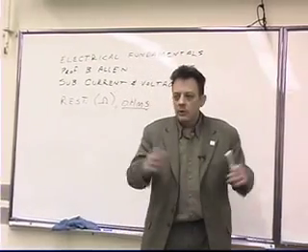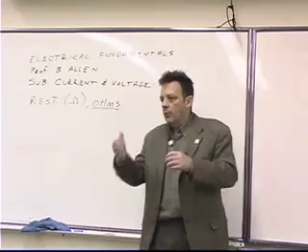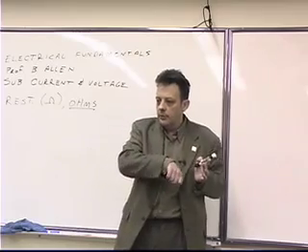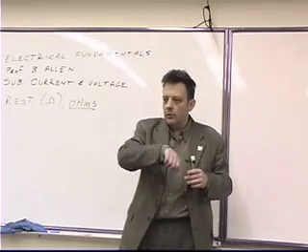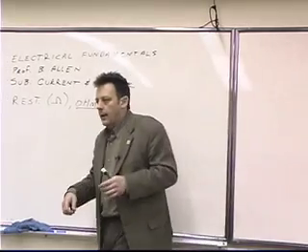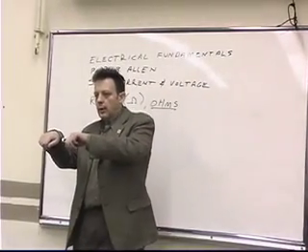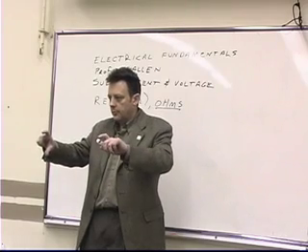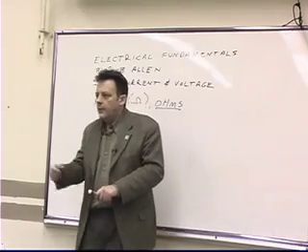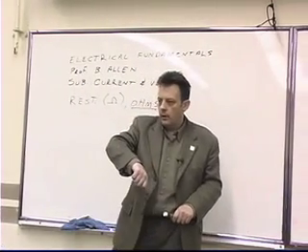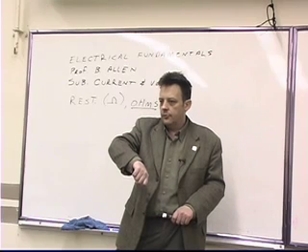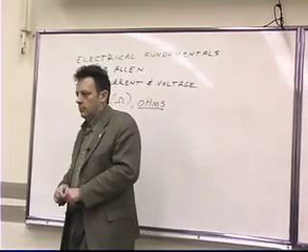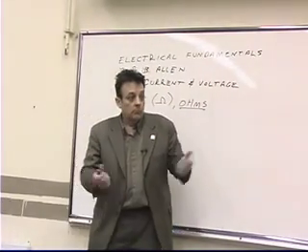Now, let's assume for a second that I pull those out and I put in a surge suppression strip, like you plug your computer into. So there's multiple receptacles. Okay? And I plug my 2 hair dryers back into the receptacles in the surge suppression strip. Okay? And then I put another hair dryer into that surge suppression strip. What have I done to the load? Tripled it. I've tripled the load.